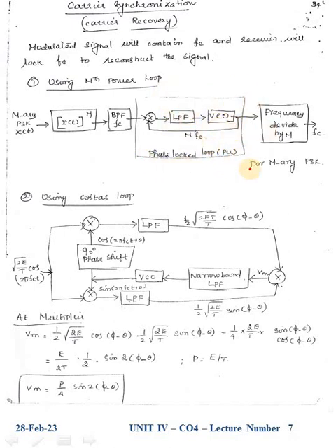We know the operation of PLL. One input will be provided to the multiplier. The multiplier receives the feedback signal, which is a negative feedback signal from the output of the VCO. So that particular frequency and the input frequency are going to be matched, and the desired frequency Fc is locked with the help of this PLL network. This low pass filter will allow only the required frequency. The unwanted frequencies are eliminated with the help of this low pass filter.